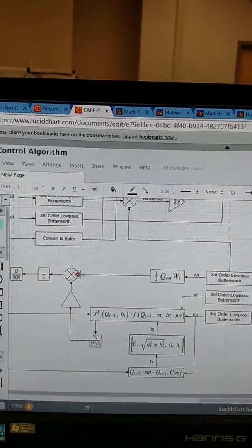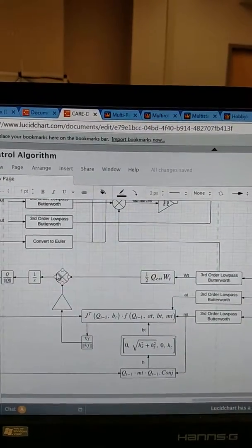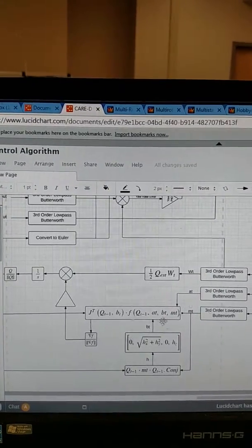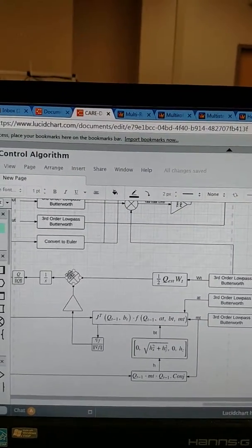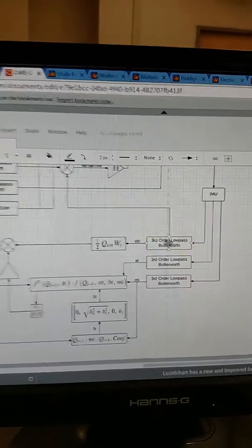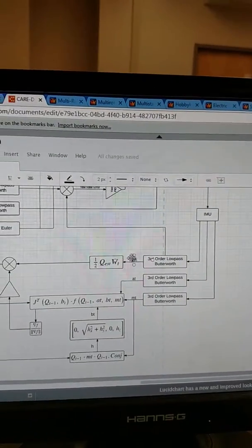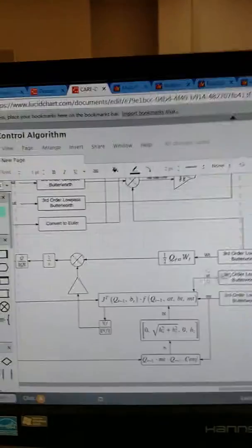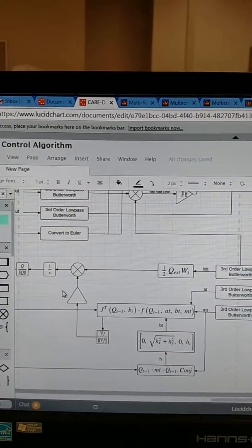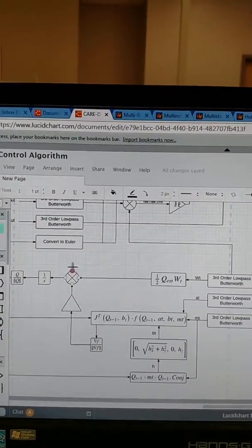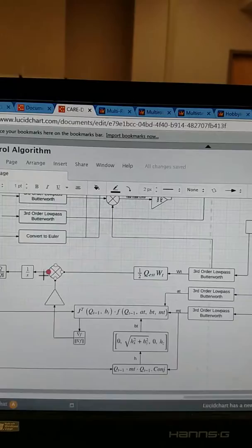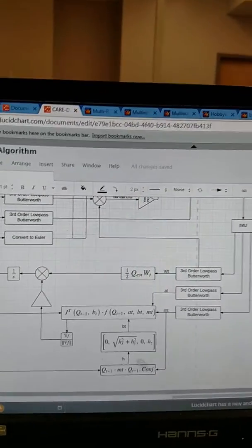Basically, the way this feedback loop works is the gyroscope is the set point, the accelerometer and magnetometer is the metric point. And the assumption here is that the gyroscope is a cheap piece of crap and that there's associated error with it. And what this PID controller is doing is correcting for magnetic distortion and also correcting a very cheap sensor as well.